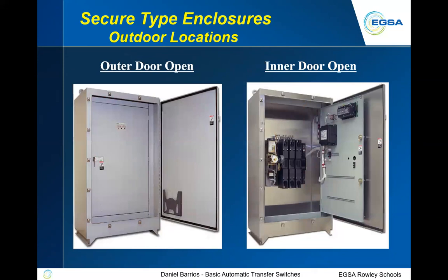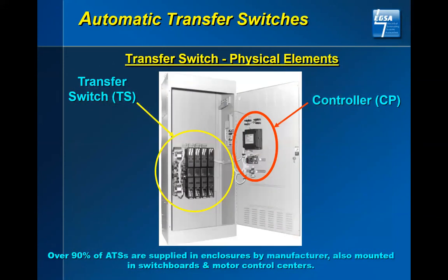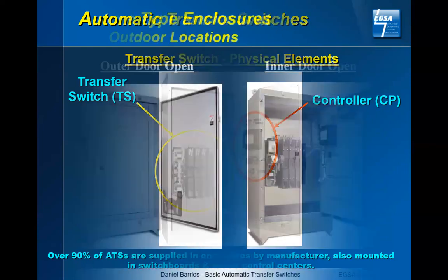Many other installations. This one here is just typically a NEMA 1 installation. It's put inside a building. If you're not familiar with those, NEMA 1 is indoor. NEMA 3R typically is outdoor, drip proof. NEMA 4X will be stainless steel. NEMA 7 is explosion proof, which typically these products do not comply with for an explosion proof installation.